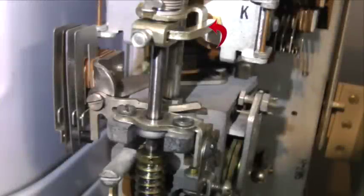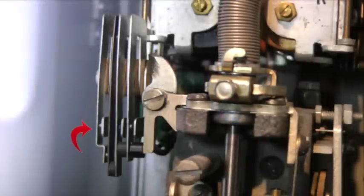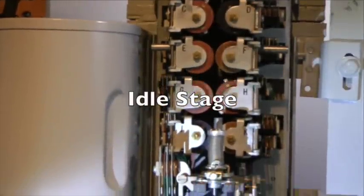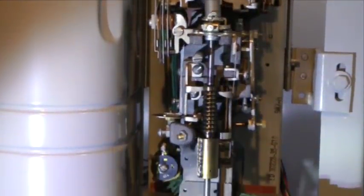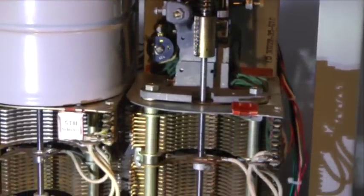As the shaft drops down, its normal pin will strike the off-normal finger. This causes the off-normal finger to pivot downwards, releasing the vertical off-normal springs. The released VON springs open the energizing path for the release magnet, and so its armature releases. At this point in time, all relays are released, all magnets are de-energized, and the shaft and all of its attached apparatus are in their normal rest position. The switch is once again in its idle stage.